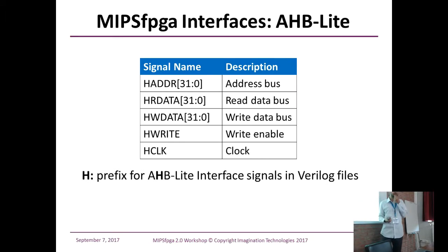The AHB bus itself, the signals are prefixed with H for the bus. Simple 32-bit address, 32-bit data, write data, read data, write signal, and a clock. As I mentioned, it doesn't have any complex features like error. Well, it does, but in terms of our use case, we just use address, read, write, buses, and the write enable and clock. So it's a simple bus which works well for teaching students.